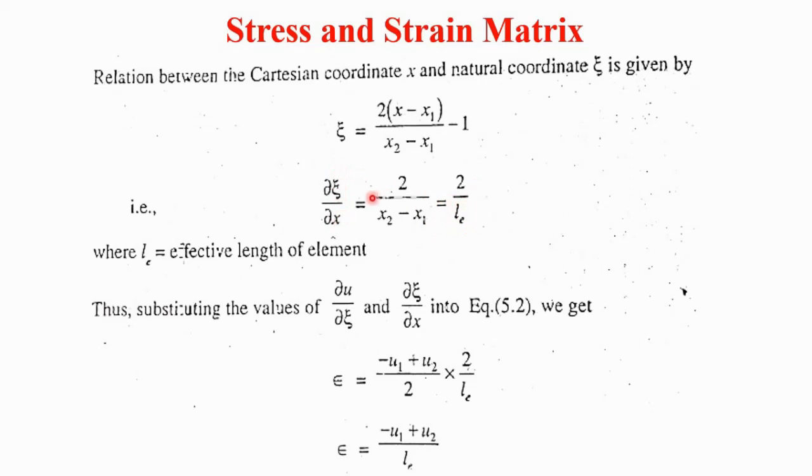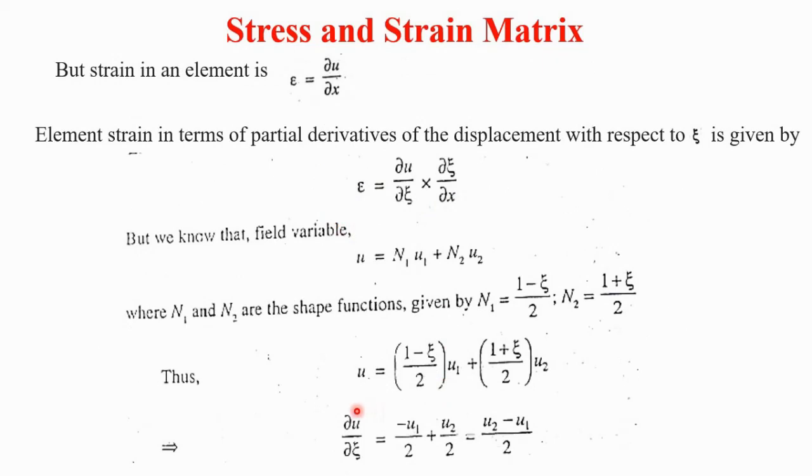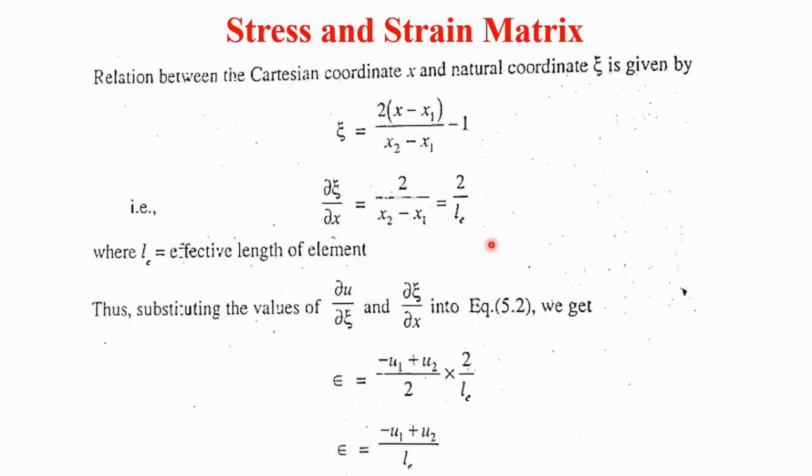Now, by putting this value of ∂ζ/∂x and this value of ∂u/∂ζ in the strain equation, strain ε is equal to ∂u/∂ζ into ∂ζ/∂x.